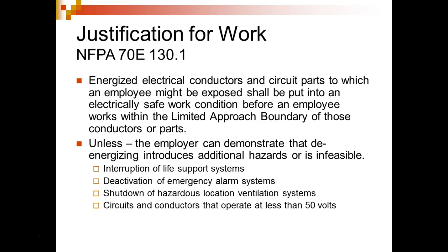When I put it on amps, it's got almost 0 ohms between the two leads because we're flowing current through the meter. So we want the meter to have almost no effect on the circuit. If it had a big R on ohms, then it would drop voltage, right? You understand? We don't want our meter to drop voltage. So basically, when you put this meter on amps, it is a short circuit.